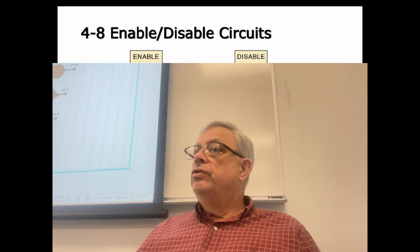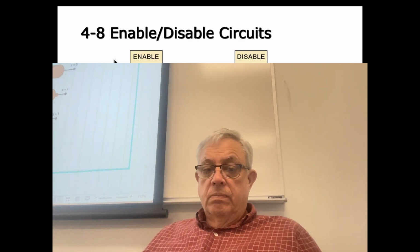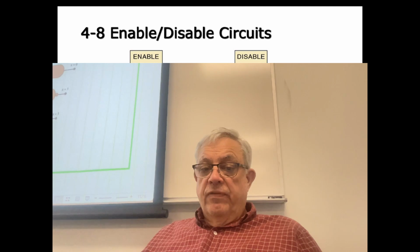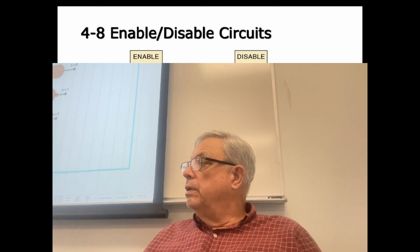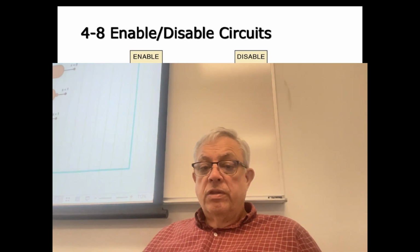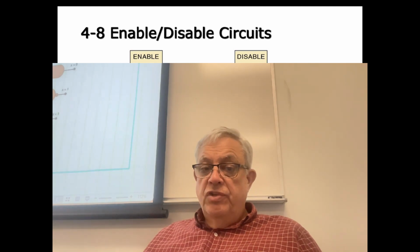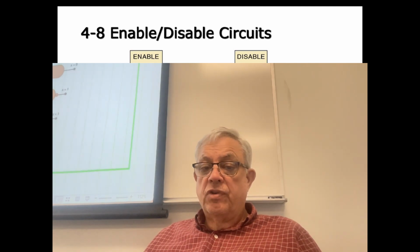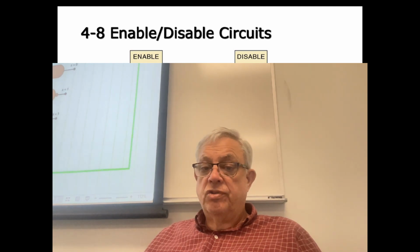We also, and you did this as a lab, enable and disable. If I've got an AND gate and I want the data from A to go to the output, then I put a control lead on B. The control lead on B says if B's a 1, then whatever's at A gets communicated through. If B's a 0, then whatever's on A gets turned off because the output is a 0.